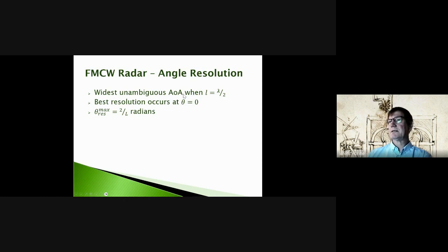I do provide some equations for you, but this also arises in antenna arrays and that type of thing. So this is a pretty common spacing criteria, right? So you typically are going to want your antenna elements spaced at this halfway length spacing.